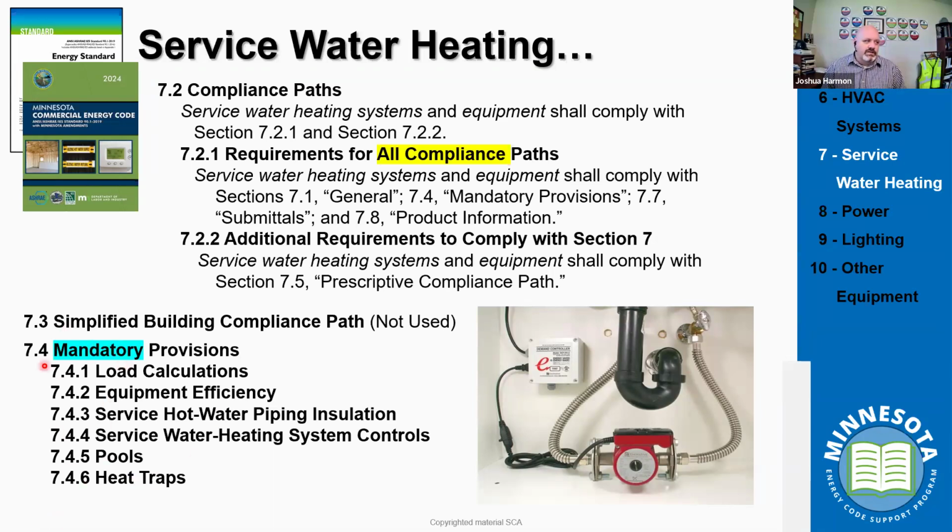So mandatory provisions, again, we're going to make sure that we understand the load calculations, we understand heat traps and different controls. Again, when we think about it, we see all the time a design come in and it's like, where did we come up with the load calculation that drove us to the decision of installing a particular size equipment? That's information that we as building officials need to be provided and review to make sure that we're all on the same page.